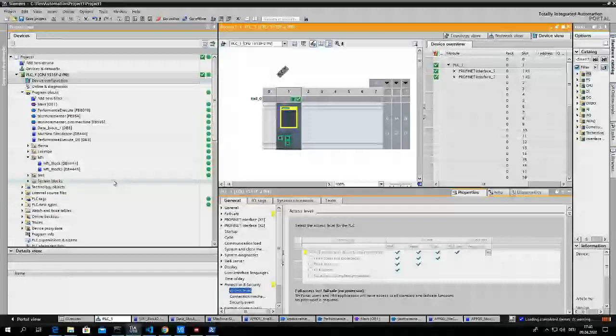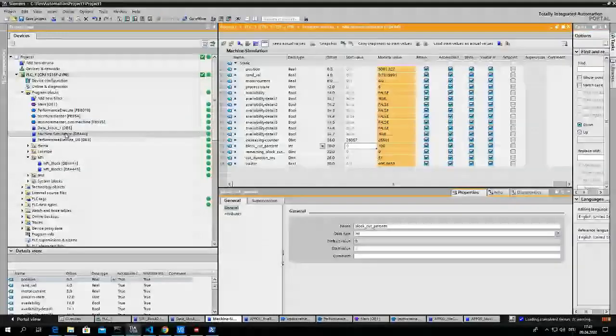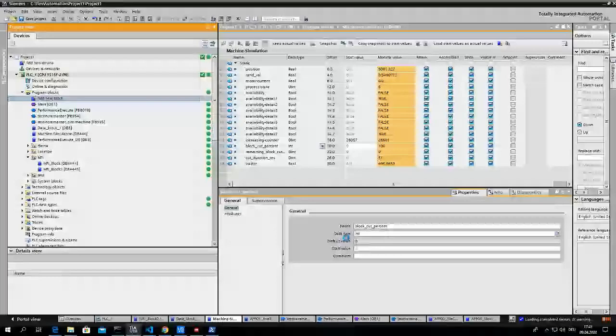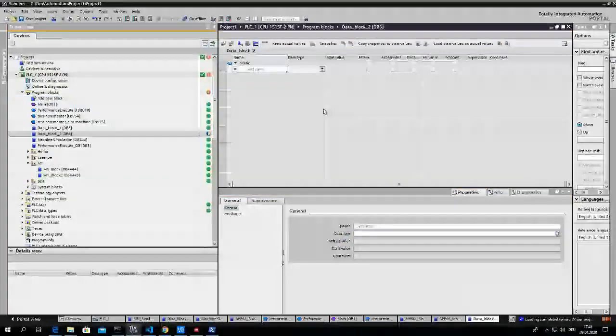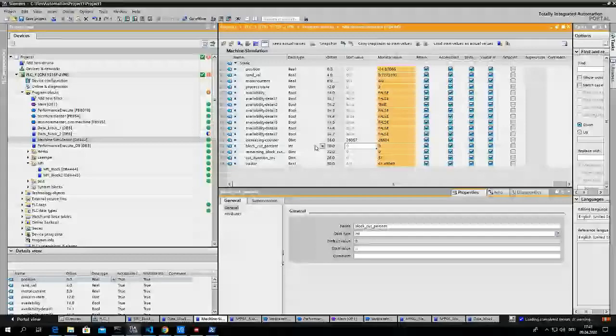The next important thing: Julian told you we currently support the S7 COMM protocol. We are planning to do the S7 COMM Plus protocol. The difference I can maybe show. Usually when you add a data block, it looks like that. But when I create a new one, I can just do this. Some name, doesn't matter. What Siemens does is make this block non-optimized. You realize that you don't have any offset row here. When I go to the block I usually use, we have this offset row.